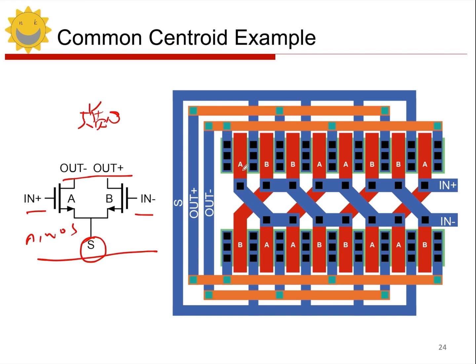So you can see the gate of all of them. We need to connect them in series. And the bulk also needs to be fully connected, right? You can see this. It's like tying shoelaces, crossing them over to connect. Now here, we need to pay attention. You can see that for B's connection, or A's connection, what will I use? The gate, right? You see, part of this cross connection is done using the gate for the connection.